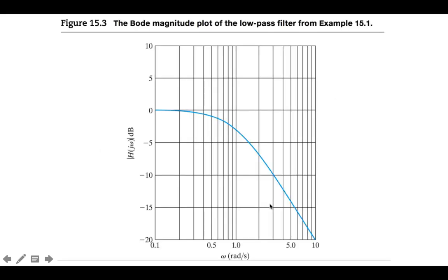So this is the Bode plot of a low-pass filter where you have a gain of 1, and you can come in and read roughly at the 3 dB down point that in this example the cutoff frequency was set equal to 1. This is also known as a prototype filter, which we'll discuss later. So anyway, that is your Bode plot of a low-pass filter.